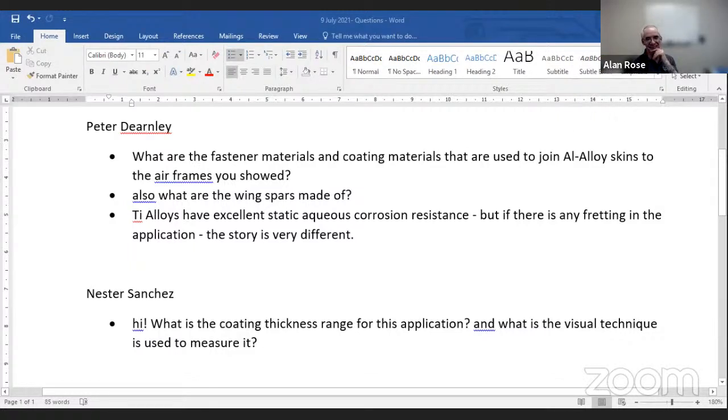You're the materials guy. Yeah, well, of course, with fretting, what happens is that you've got two materials generally rubbing very slightly against each other, and you tend to get very rapid damage, loss of the oxide coating, which tends to give you that nice corrosion resistance. But now what you can do in computation is take that into account by saying, what happens if I make a hole through this nice area here, or rather a damage on this nice area here? Now, what kind of corrosion rates do I get? And how do I deal with that? Okay. So we can take that into account.